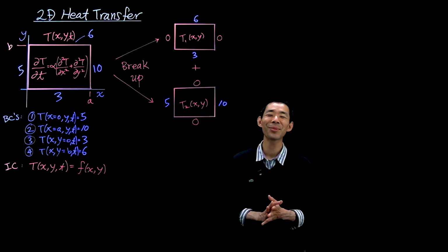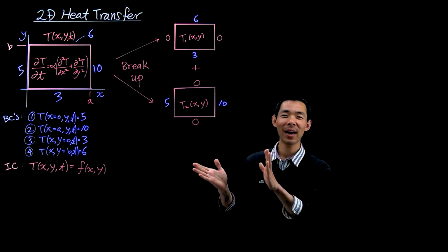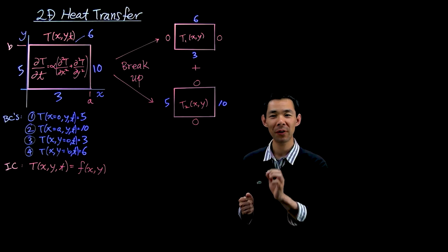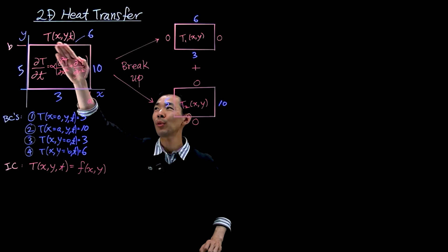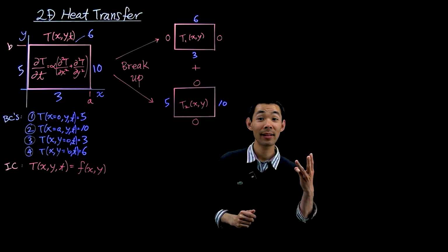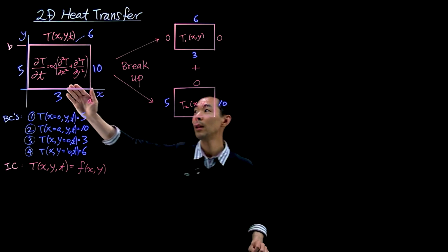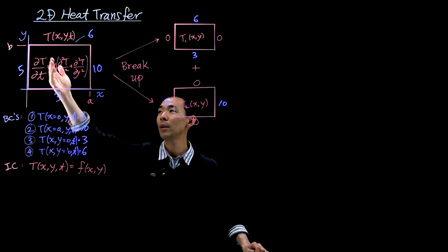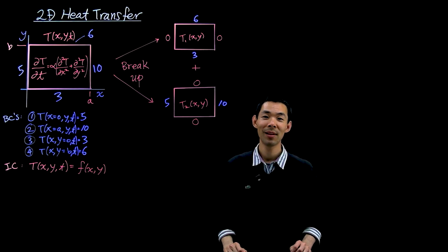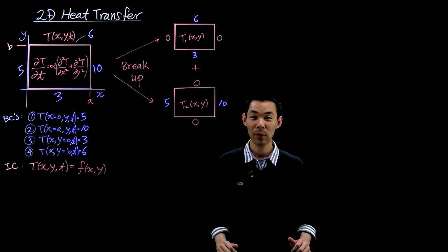All right, let's work on the fully transient 2D solution. I've kept the same diagram because a lot of it can be reused. I've made a couple of notable changes. First, the temperature profile we want to solve is now a function of x, y, and time. So three independent variables that the temperature depends on. Naturally, because we're solving a transient problem, we're going to have our partial temperature, partial time resurrected. So now it's a non-zero left-hand side. We're solving the full 2D transient heat equation.